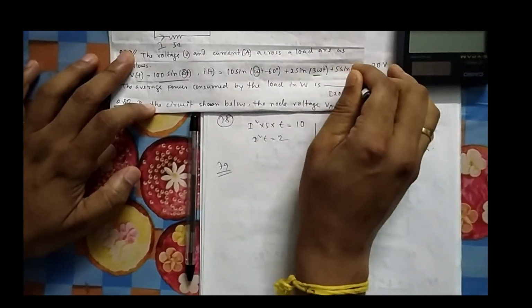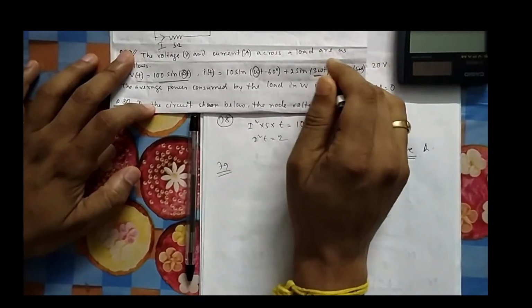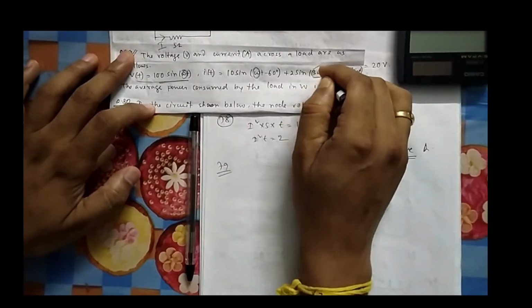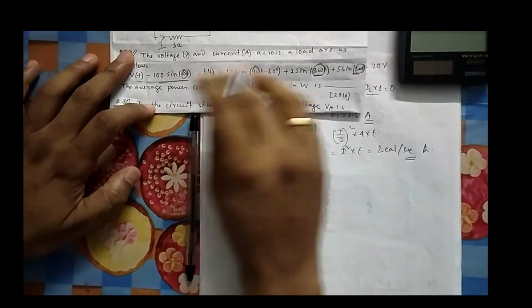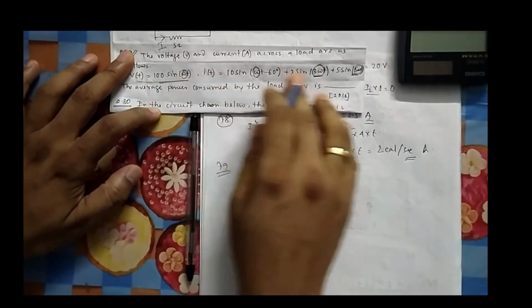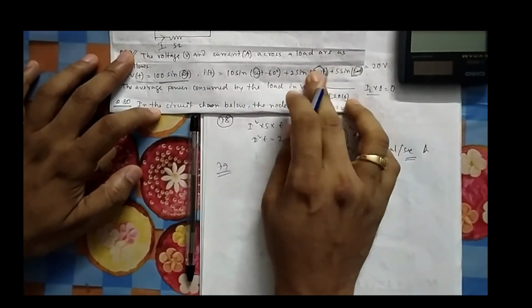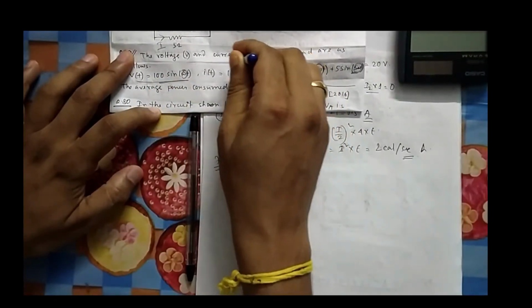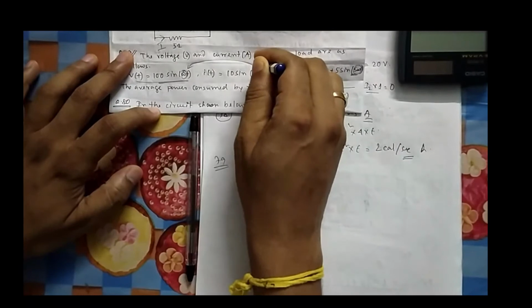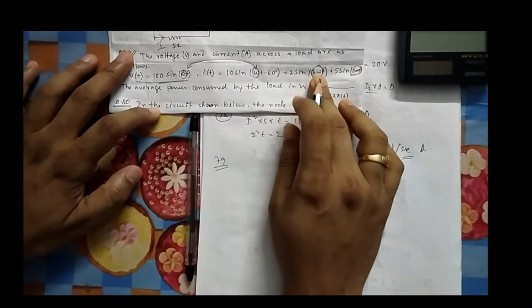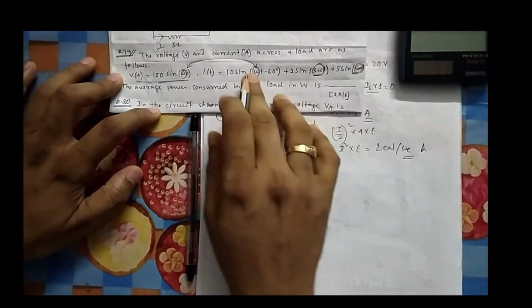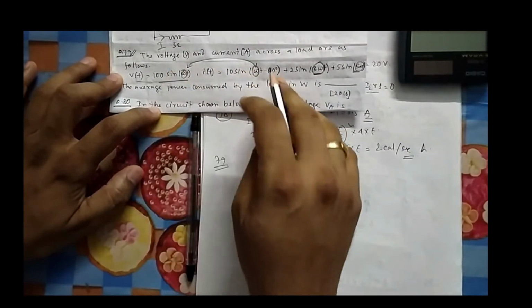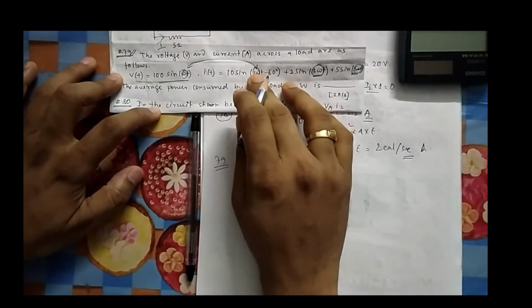These two are current harmonics, third order harmonic and fifth order harmonic. But for the third order frequency and fifth order frequency, you don't have any voltage, so power will not be generated by these two. Because in power you need V and I, only the same frequencies will be multiplied, because this voltage cannot be multiplied with these currents. So power consumed will be only between the same frequency, because I have explained in one circuit with different frequency also.